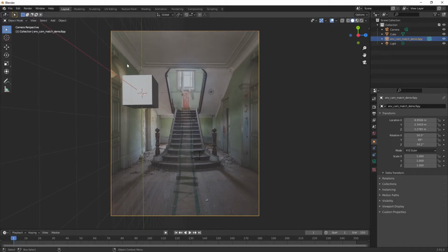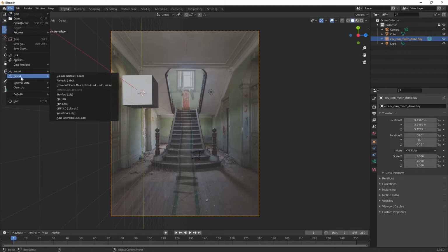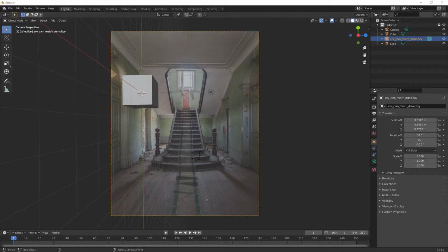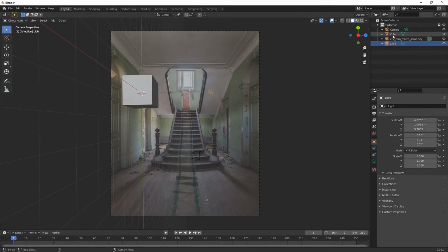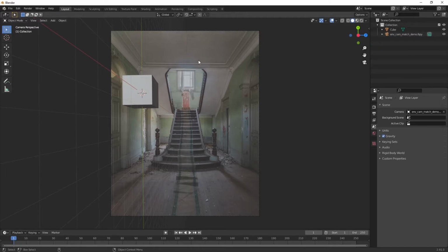Or imported properly, and now we're just going to simply take this into Maya. That's it. We're just using Blender right now as a middle point since there is no Maya plugin to import fSpy files, but it just makes sense to simply use Blender to import it and then export it. So I'll go ahead and do File, Export FBX, and you'd want to make sure to not have anything selected. You can delete the lights and the other camera so it doesn't confuse anything. Maybe just leave the cube there for orientation.